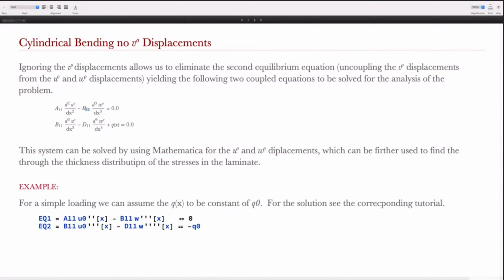So in-plane stretching and bending are coupled. If the plate bends, I'm no longer assuming the in-plane displacement to be just a direct function of it, but it is coupled through the stiffness coefficient B11. And this is what we're going to solve today. Okay?